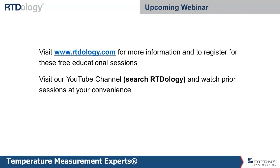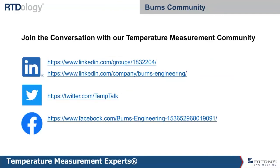That's typically done at maybe 150 degrees C. Kind of anything over 212 F or 100 degrees C probably does it pretty well. But again, it still means that there's probably a hole in the probe and it needs to be replaced. And just the second part of that question, Bill, was does IR ever go up, or is it usually just one-way? Yeah, that's the case where it would go up, is if you're drying out the probe, you notice that it goes up. All right, very good.